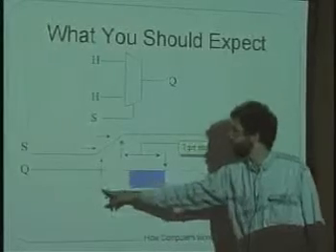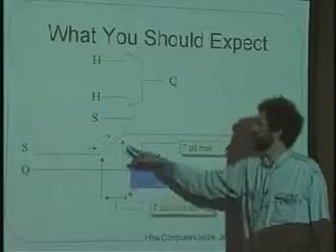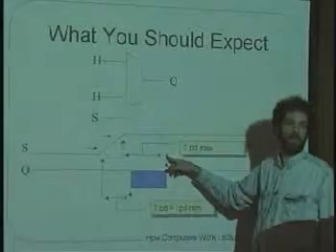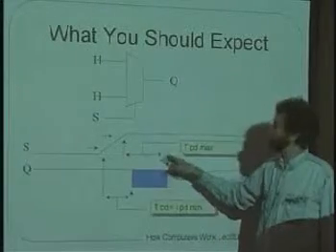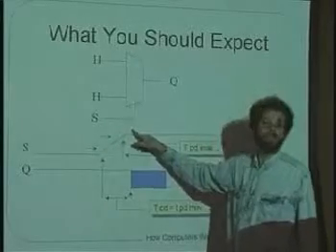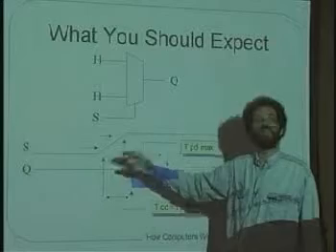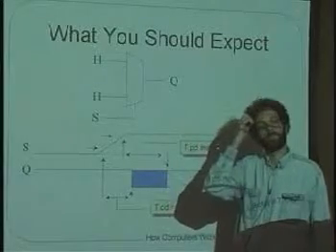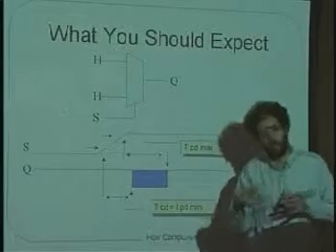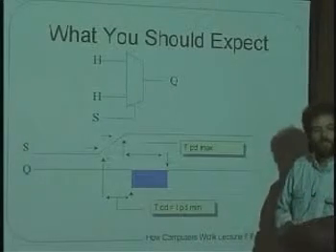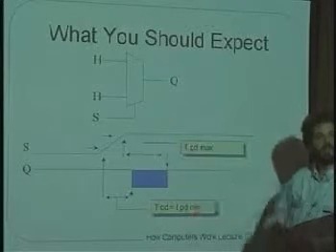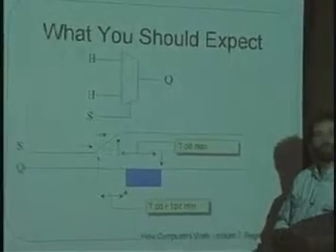So this is from garbage in to garbage out, from new valid value in to new valid value out. And that's why here we're starting to show you that signals don't transit instantaneously from a 0 to a 1. In fact, they take a little bit of time. We're just starting to hint at that. And in the class, as we go deeper and deeper into the circuitry, you're going to see how that slope, in fact, comes about in natural circuits.